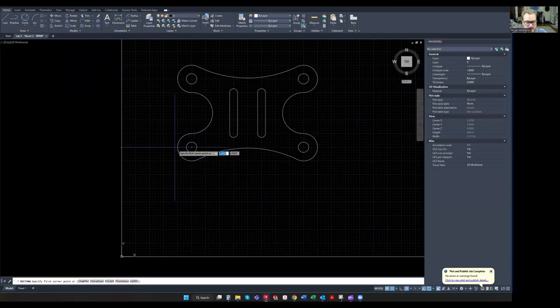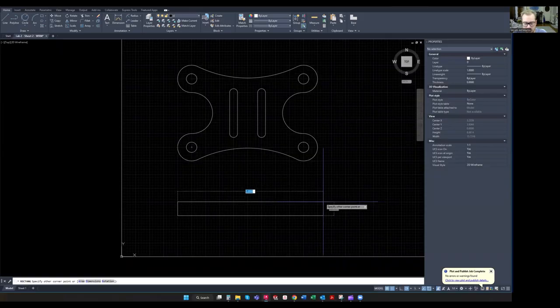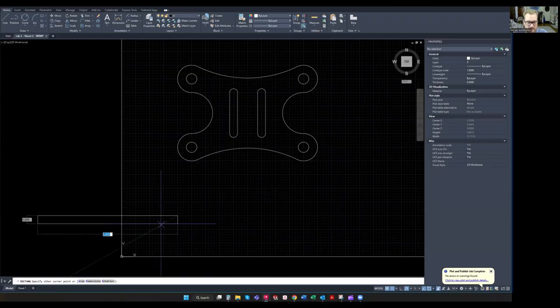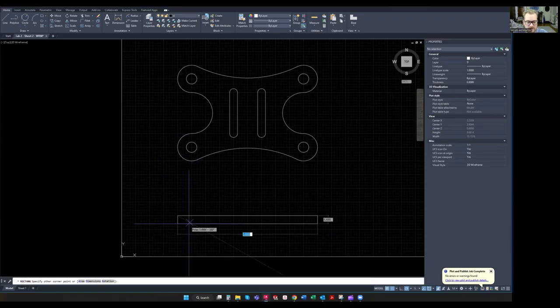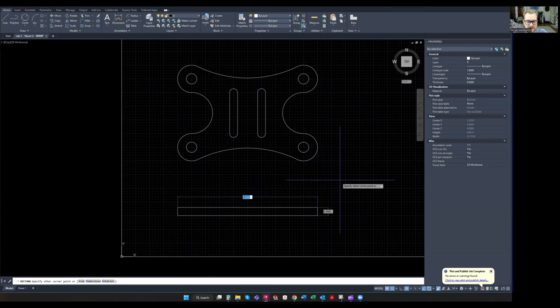I'm going to go ahead and start this an inch below, 2 inches below. I'm going to say, let's go 2.5 inches below. That's below where this circle is, below where this quadrant is. So starting here, I'm going to drag up and to the right, D, enter, and that's going to be 5, enter, 0.3, enter. And now we have our rectangle. We just have to snap to a quadrant, and I'm going to snap it to the top right here, just like that.